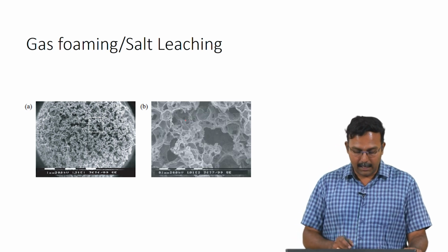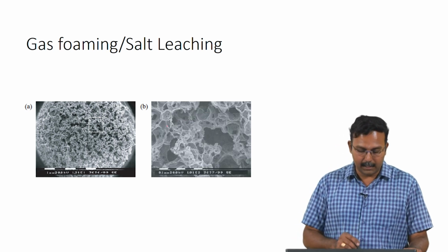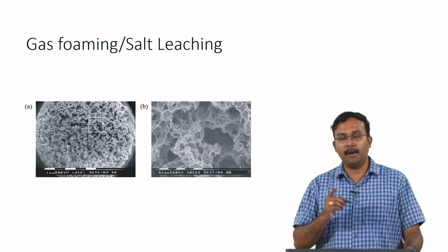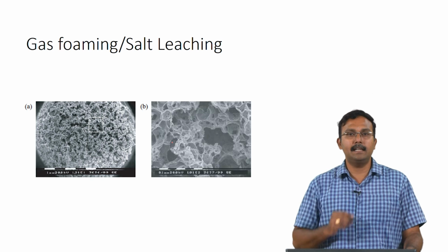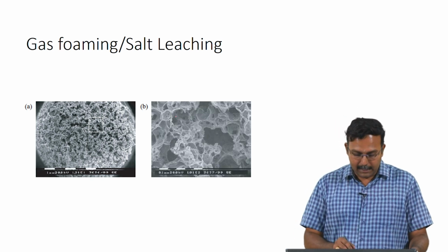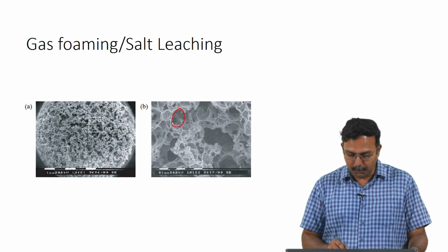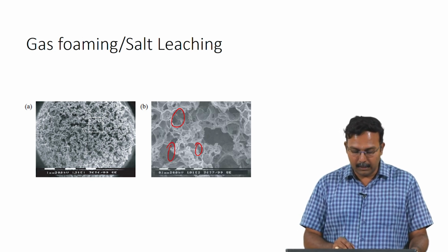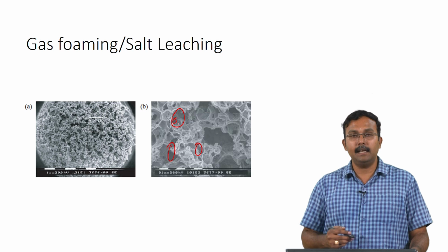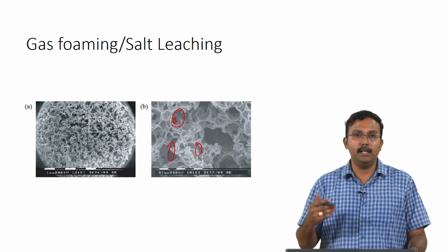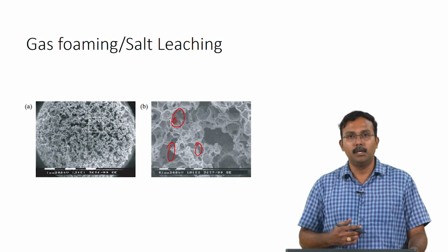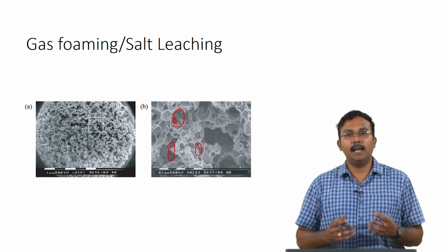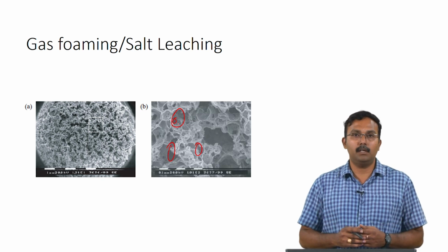So, what you see here are pores which have good interconnectivity. Because the gas is actually pumped through the pores, you would have nice interconnectivity for the pores. So, you can see that there are lots of pores. You look at the SEM image. So, you see that there is a pore and these are some of the pores, and as you see most of these pores are very deep, and even in this particular pore you would see there are smaller pores which are much darker in color, indicating that they are much deeper and they are actually probably interconnected to some other pore.